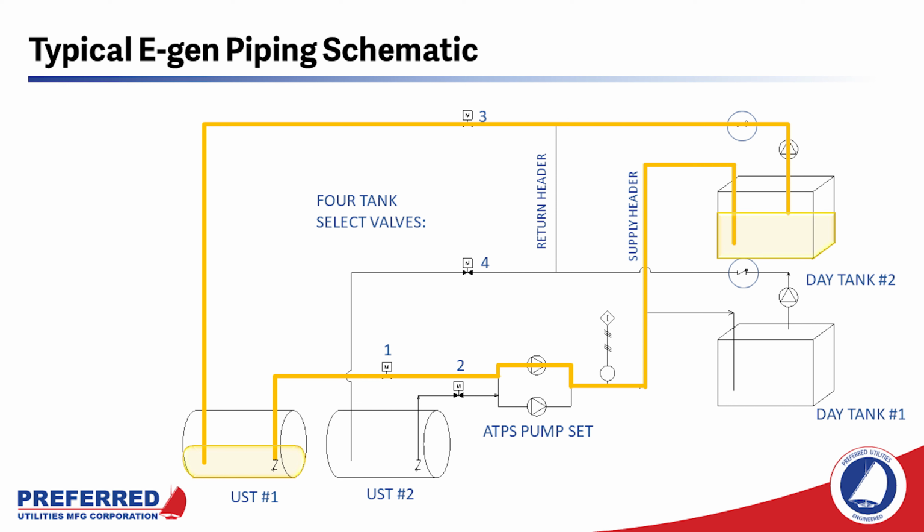So the pumps evacuate the pipe, and then it's atmospheric pressure forcing on the main tanks, pushing on the pipe that pushes the oil along the pipe. And the reason that there's an elevation field in the pump and pipe sizing program is when you get up to higher elevations, there's less atmospheric pressure there to push the oil through the suction side of the system. So I'm always careful, especially if I'm doing a job that's high altitude, to make sure that I include that elevation number, because there's just less ambient air pressure there to push on the suction side of our pipe system.